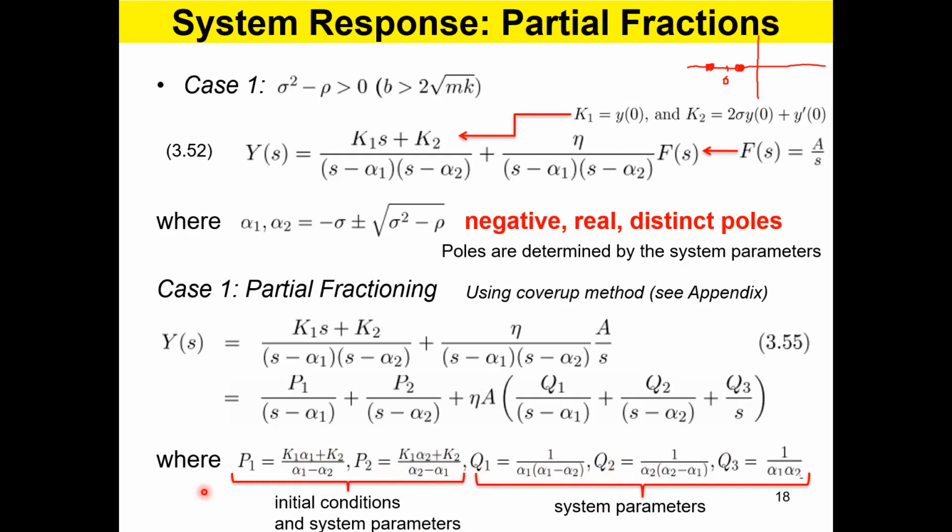They are the system components. Your damper, your spring, they have to be part of every term here. Okay? You can't have a response without the system parameters. Now here, the first two terms, in addition to the system parameters, you have the initial position and velocity, but you don't have external force here. But if you go to the next three, you have the external force connection, but no initial conditions. Okay, so the five terms in two groups, they're very specific in nature.